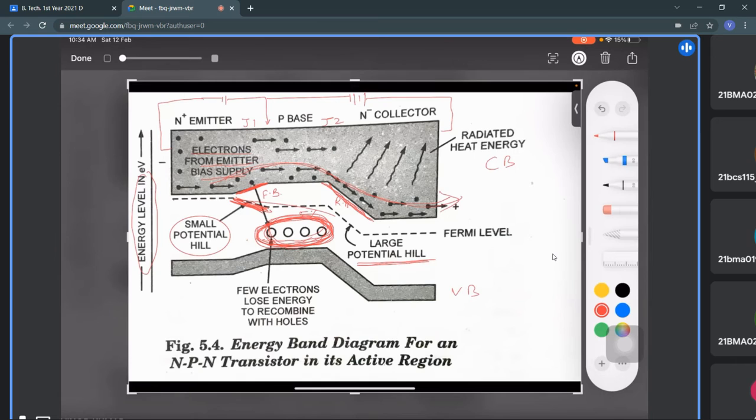Right. Why are these holes here? Because this is p-type, and in p-type it is above the valence band, because of the doping impurity: boron, aluminium, gallium, indium, like this. This is p-type. So if you remember, here this is the acceptor energy level in case of p-type semiconductor. So they are going to recombine, 5% of them. The rest will go into the conduction band because supply is given from here, so these electrons which are coming from here are in the conduction band.